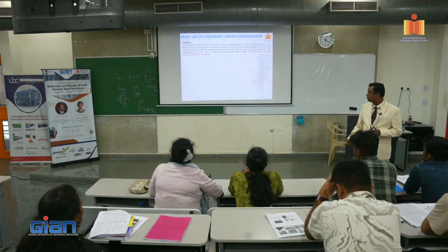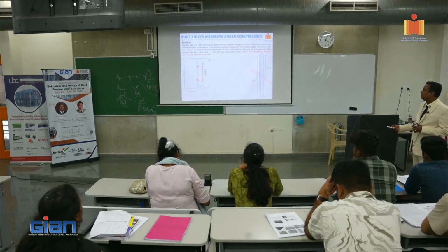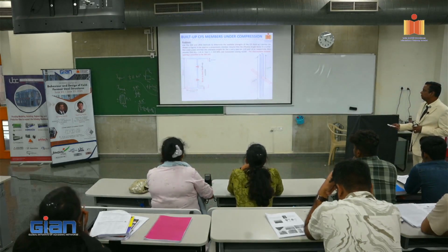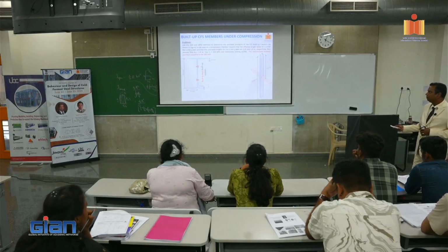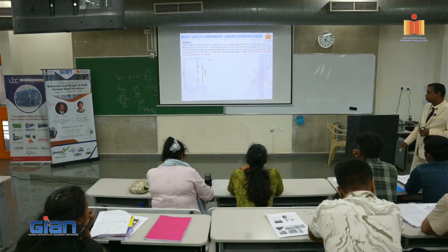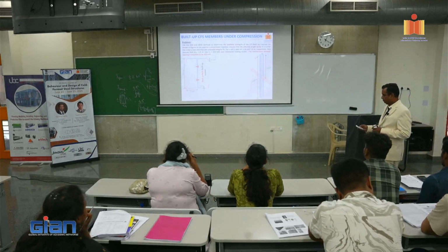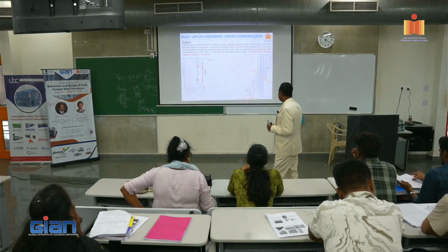Right? We'll go slowly. So this is the built up section. Right? So the depth is 200 mm, the lip is 15 mm, and this is 75 mm. So back to back built up section. As you said, the screw is in one direction, other direction. This is 2 mm, right?